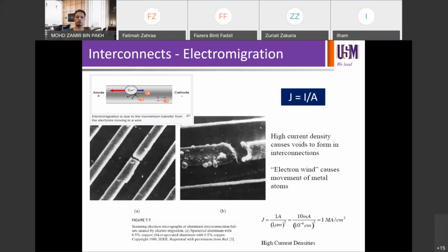Okay, so you won't have this electromigration instantly. Maybe you won't see the effect in 1 hour, 2 hours. Maybe it takes days or weeks or years depending on the condition of the conductor, right? So there's no fixed duration of electromigration, but rather it evolves over time. How fast you develop the electromigration really depends on the parameters that you have for the wires, for the current, and for the atoms that make up the conductors and so on and so forth, right?